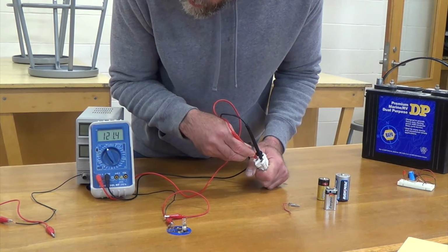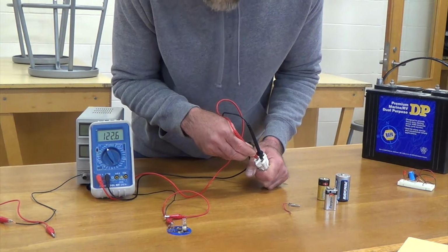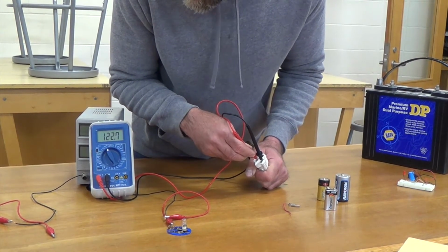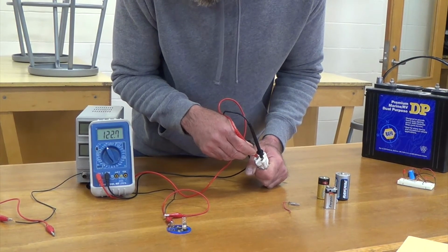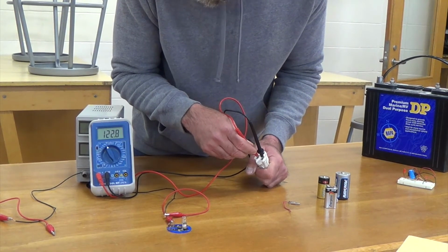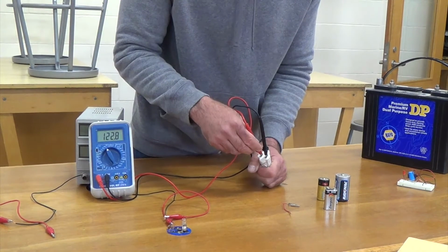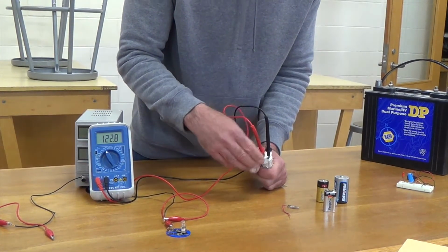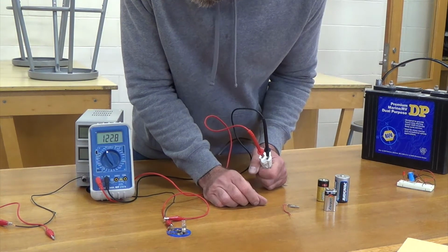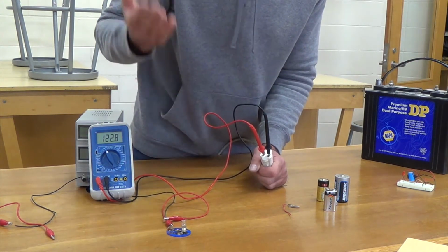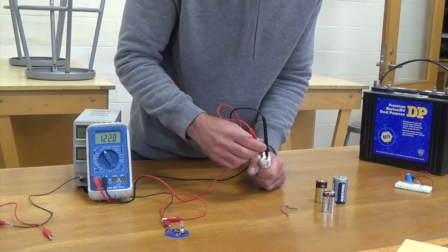I get about 100. It's supposed to be about 120. But in any building, you're going to have variances. You're going to have up and down. This is 122.7. So that's why it's important with electronics that require a certain amount of current or voltage that you run it through a spike bar, because you can get up and down spikes and drops in that